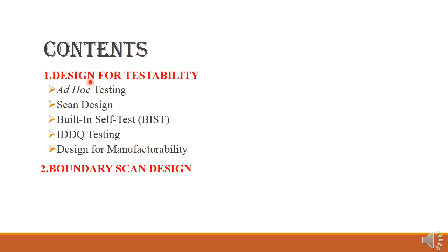If we go for real estate, there everyone will say the word location, location, location. Similarly, in IC design, we use the word testing, testing, testing, because testing is very important in IC design. Here there are three main categories. First one is functionality test or logic verification. Second one is silicon debug and third one is manufacturing test.